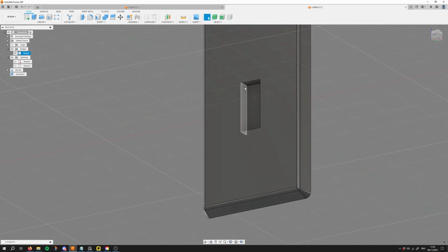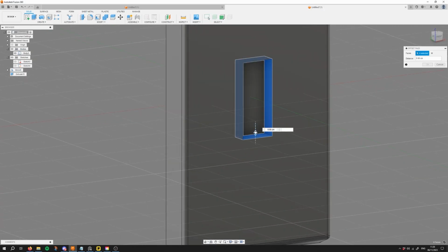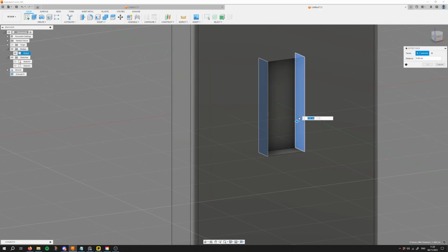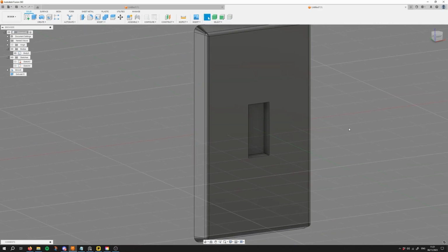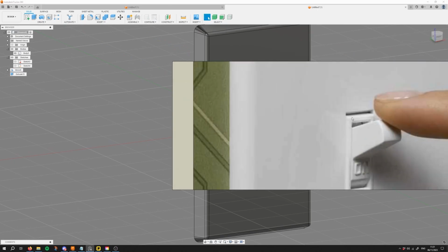The same thing can be done if you want it to create just a little bit smaller. You can press Q, select all your faces, drag it in or out. Want it a bit shorter or less wide, press Q, drag it in or out. The next thing we want to do, if we look at the references, is create this little extrusion here.